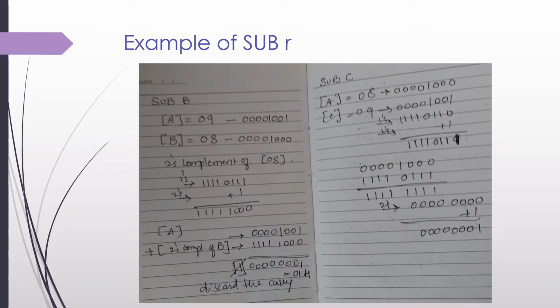There is one more example we have seen here, the opposite of it, that is when you get the negative result. So subtract C, the content of A is 08 and the content of C is 09 we have taken. The whole method is the same. When you come to this, the result after the addition of accumulator as it is plus the 2's complement of the subtrahend is 1111 1111, which is not the result. 8 minus 9 should be 01, isn't it?